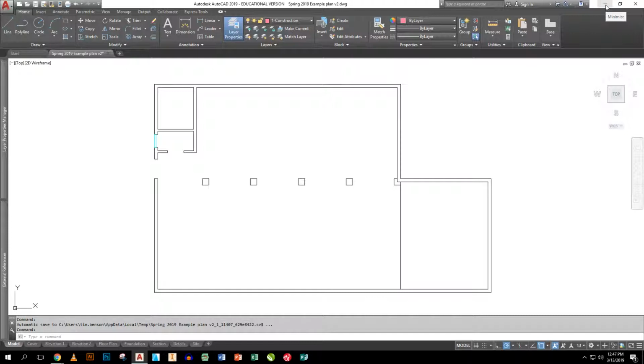Obviously, the doors go all the way to the floor. So we'll just start dropping some of those in and work our way out. Now, first thing I'm going to do is make sure my current layer is my wall layer, and I'm going to mark in the very center of this wall right here. Okay. Now, the easiest way to do a window is to offset.